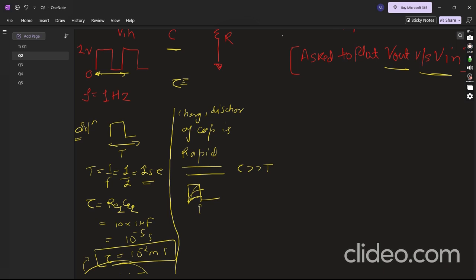If a capacitor charges up to this point, not fully charged, when a positive pulse occurs, then in the next cycle, when the pulse is zero, the capacitor has to discharge, and it will not discharge to zero. It will discharge to somewhere around that position, and then a new pulse comes and the capacitor charges again. We can't simply say at what value the capacitor charges. We can find it by equation and solving the question, but it becomes quite difficult.